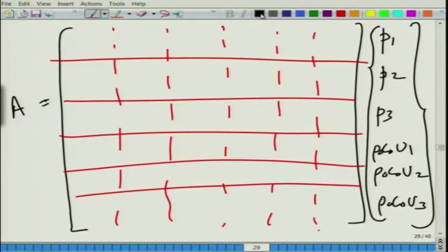So, here what we will do, we will write down the momentum equation in the first duct at the very first. So, A14, this term will become minus j k naught. You see, because here you have a state variable x dash. So, what it really means is that del P1 by del z is equal to minus j k naught times rho naught c naught u1. So, here we write the momentum equation first. Now, this is with the understanding this is the A matrix. So, I am just sort of rubbing it off.